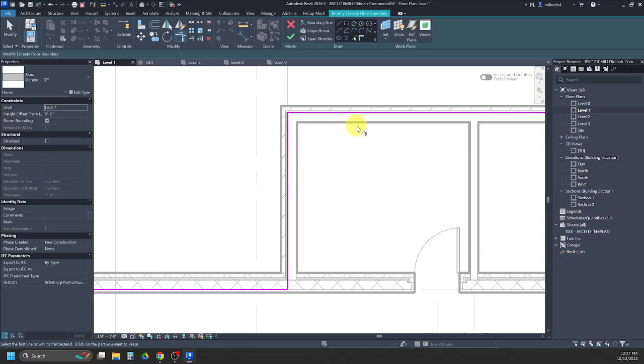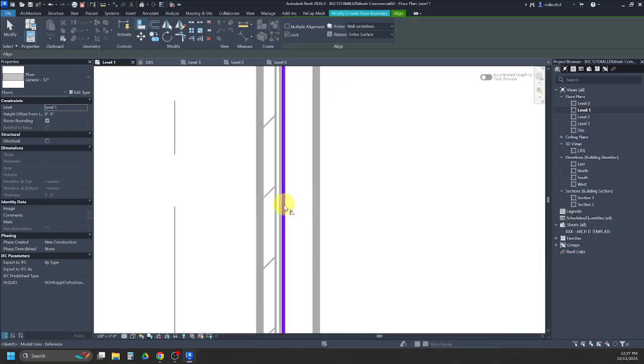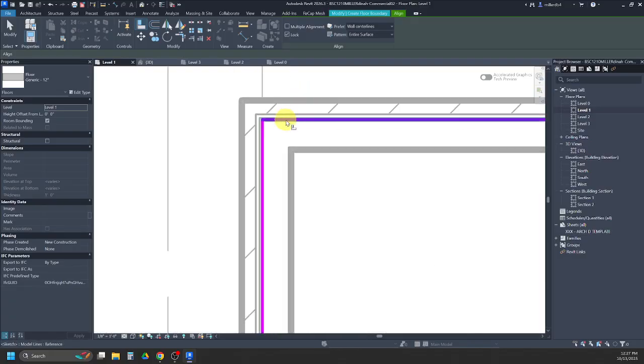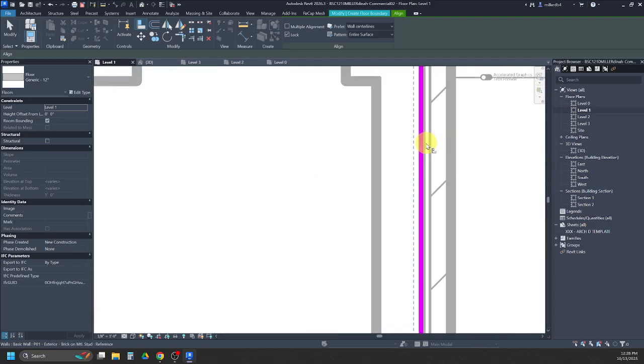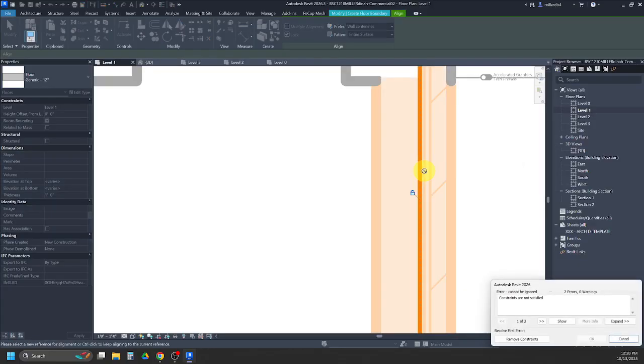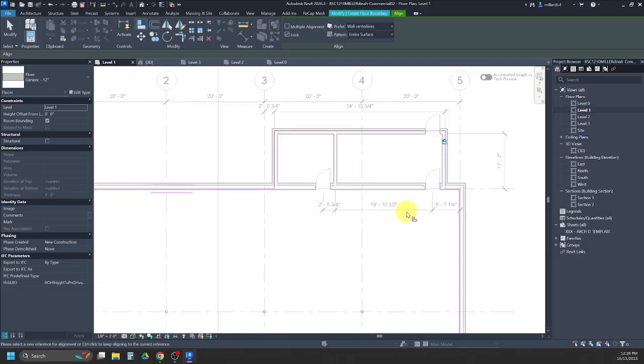I can also check on my walls up here with a line. So I can use keyboard shortcut AL to click on the face of stud, which this one I believe is already on. This one I might have missed a little bit. I think I got that one. I think actually I might have gotten all of them. Yeah, because that's my face of stud. But I can even then check that it's going on that face.